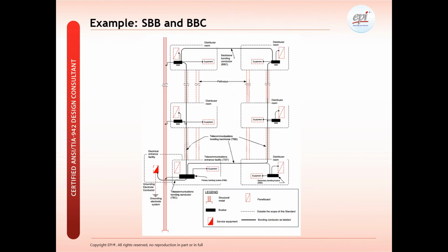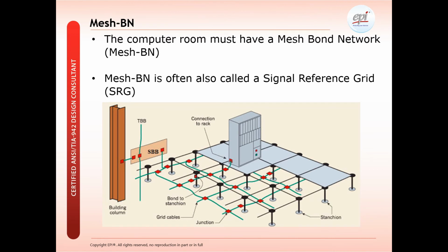Within a TIA compliant data center, we need to have the 3 grounding systems. This particular slide here is an example of how the telecommunication clean earth or the telecom grounding system should be implemented to ensure we have an equipotential grounding system to protect the ICT equipment from high frequency noise and from electrostatic discharges.